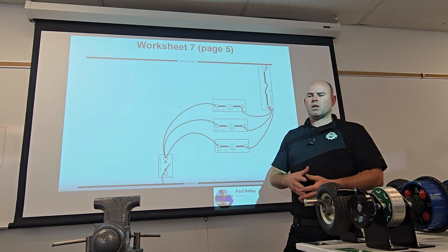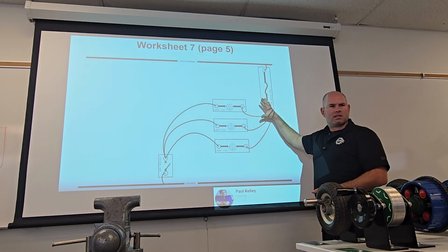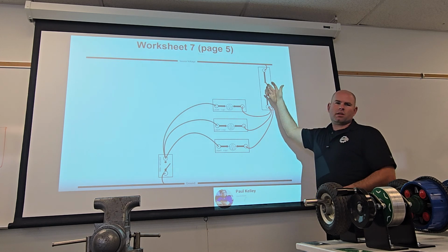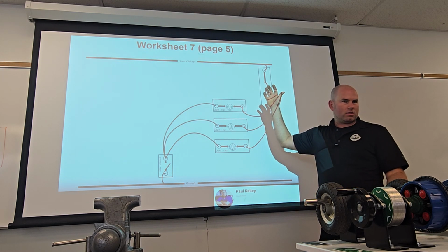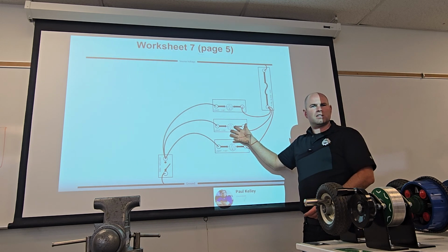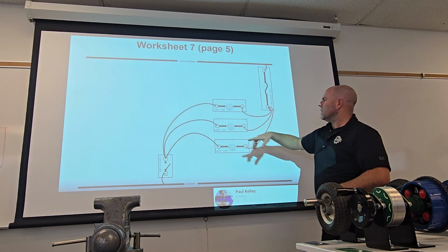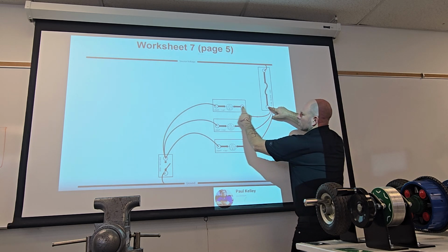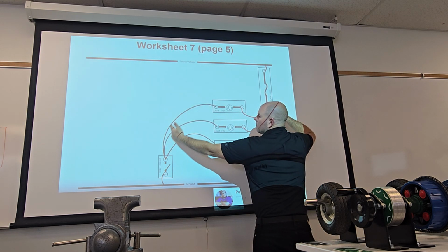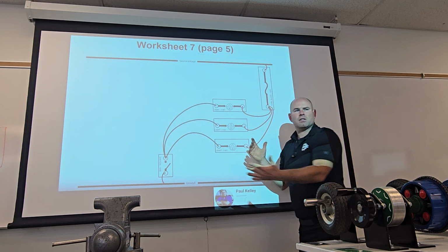So if a customer comes in with one tail light out and the wiring diagram is like this, you can check the fuse, but you're wasting time. You already essentially checked the fuse when you noticed these 2 lights work. Make sense? Then from there, you can say, well, if this light's out, then I'm really just going to look at this circuit from here to here because that's the only point the problem could be. And then if you look at it, you're back to really a series circuit.